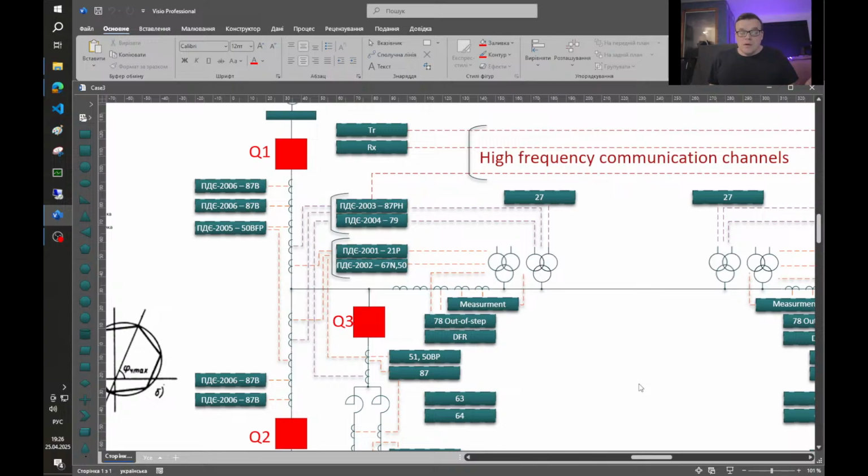And the last protection command is command 16, and we have numbers that everybody in Ukraine knows what the number means. So the 16 command signal is used before any trip for teleprotection with the third stage of the directional neutral overcurrent protection.